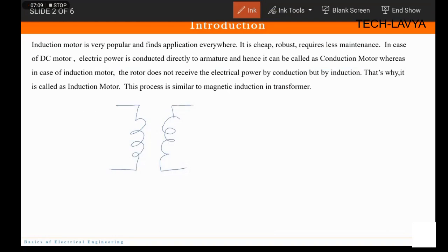They are electrically or physically isolated. But current is flowing in coil 1. Now because of the flux linkage, a magnetic field is produced in L2, which is another coil, and this type of magnetic field production is called mutual inductance, right? So this is represented by M.